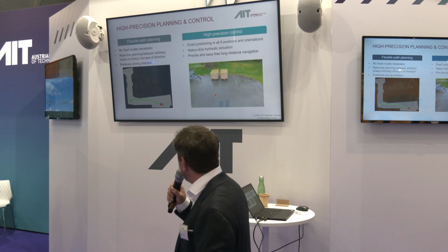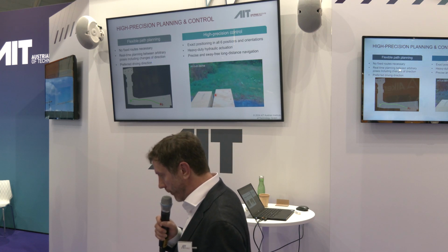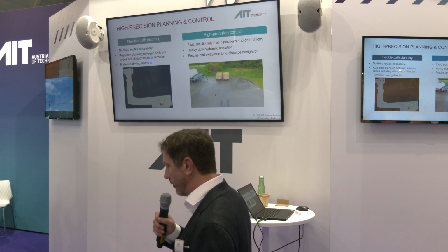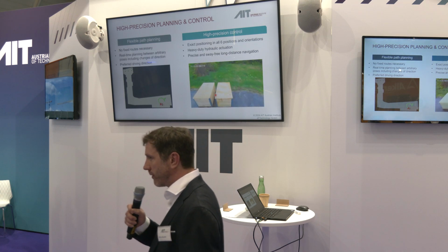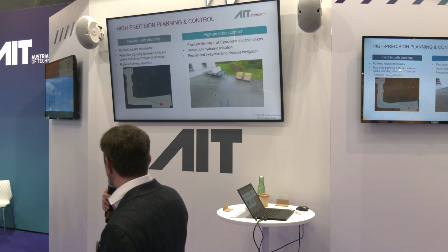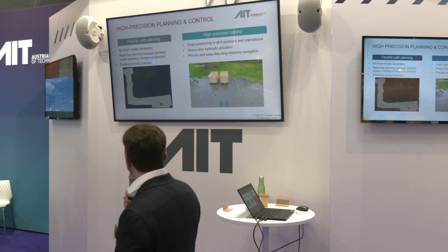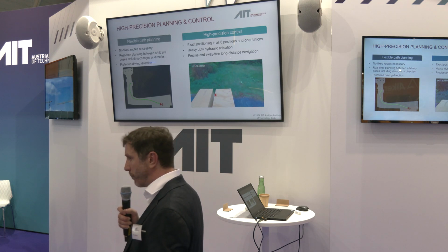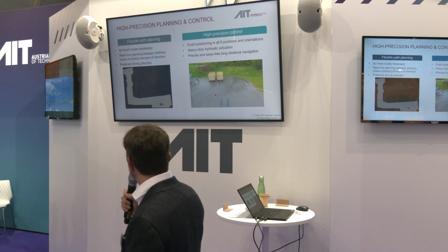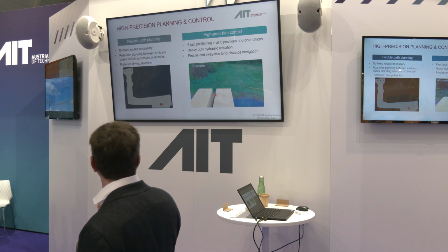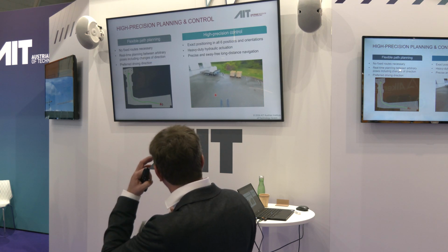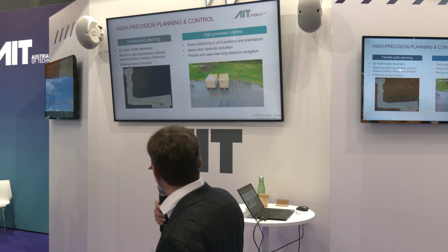Okay, on the left side we see that for the path planning we have an approach which replans all the time. Whenever we give the system a new query, more or less, consisting of a pallet to pick up in the current position, it will determine completely new paths within the environment, which is already mapped in that case. So this means that for every pallet, the path is planned anew, and there's no pre-built paths, but they are optimization based. And it's real-time capable, and we can see here already that it works together with our control mechanisms to then in the end pick up the pallets.